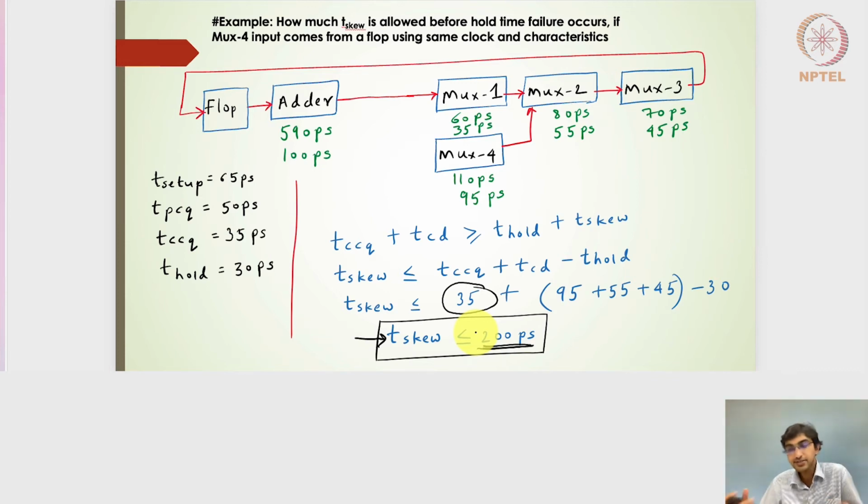So this completes the static timing analysis part, where we had seen the clock skewing effect for the pulse latch, and also we considered some examples for the flop designs, and what the allowable skewing factor is that we can choose for a clock for a particular data path subsystem example, right?